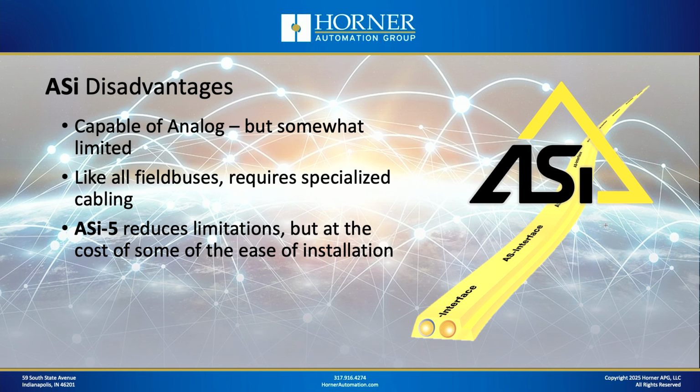And then another, what I would think of as a disadvantage is ASi 5, while it offers some really nice improvements, it also takes away some of the advantages of ASi by having much more strict installation requirements with ASi 5 than with traditional ASi 3.